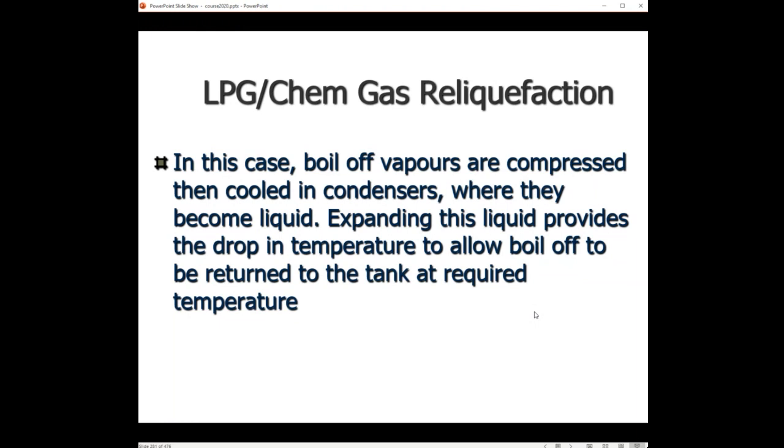The most important thing is to take away the heat out of the tank. So take away the vapors out of the tank. So theoretically, I repeat, theoretically, sending the vapors into the atmosphere would also be a solution to keep the tank cooled down. But it's not allowed anymore, to make things short.